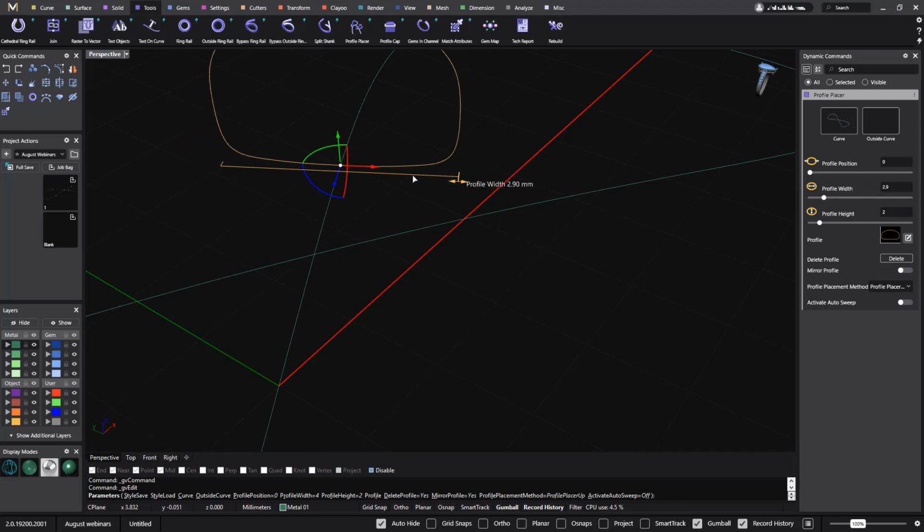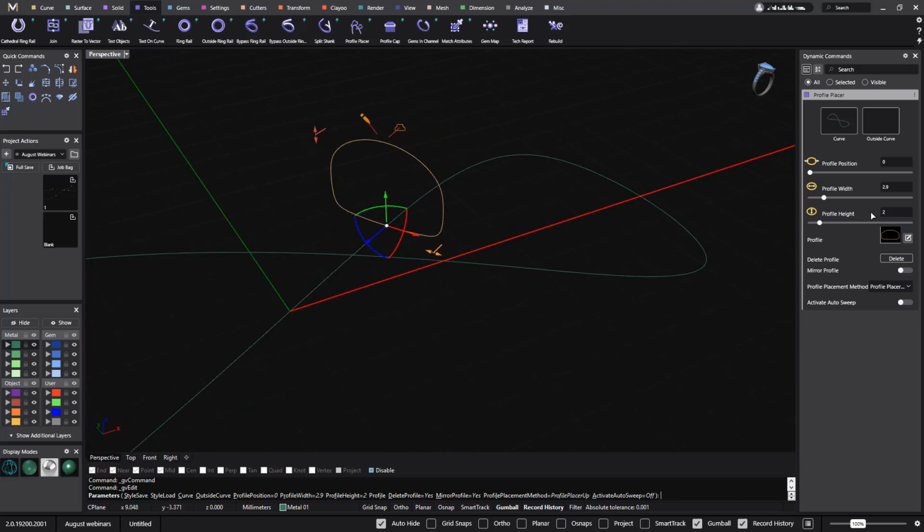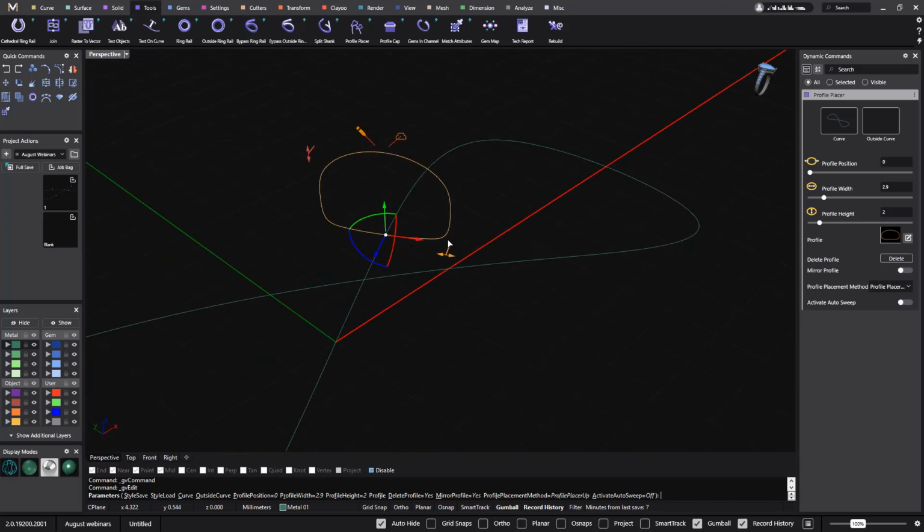As you know, you can do it from the viewport, or you can do it from inside the tool settings in your right panel stack. So now, if you want to be very precise, you don't need to go here. You can just go here and say, okay, because I want to set 1.5 millimeter stones, I will go to 2.5 millimeters, this area here, because this is where I'm going to set the stones. And now the height is 2 millimeters. 1.7 will be okay for me.